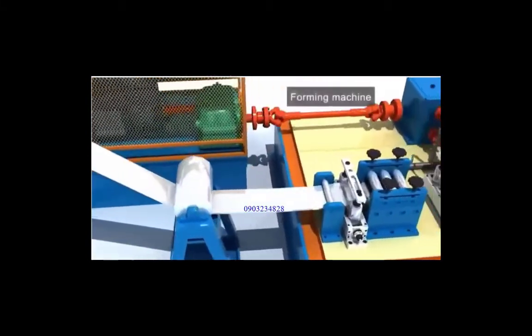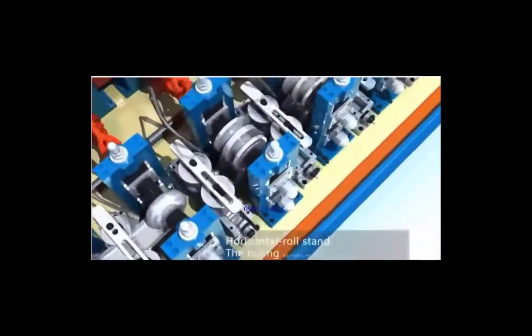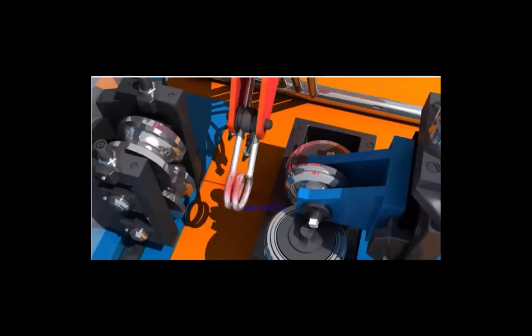The forming machine is used to turn the flat steel strip into a round shape by horizontal roll stands and vertical roll stands. The guiding device is used to adjust the position of the welding seam before welding, and has the functions of up and down, front and back, and rotate three-dimensional adjustment. Then the high-frequency induction welding machine heats the open area to melt.